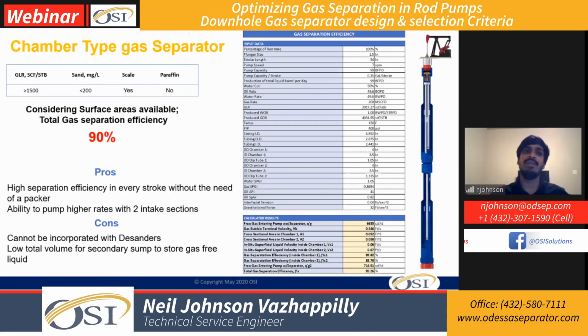All right, with this chamber type, considering all the parameters that we consider in our calculator, we actually get much higher separation, even compared to a packer type, just for GLRs. The reason is that we calculate the separation efficiencies individually in both of these chambers and then average them to get an overall efficiency.